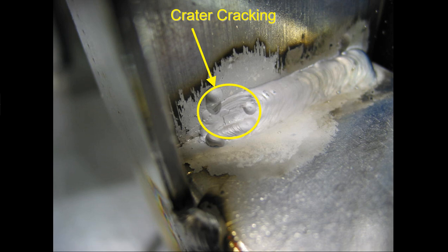The welds are far more ductile than the base metals are, especially with the 6000 series. So your responsibility on a spot like this would be to take your die grinder, take a little bit of this out, clean this away a little bit, and create a proper termination.